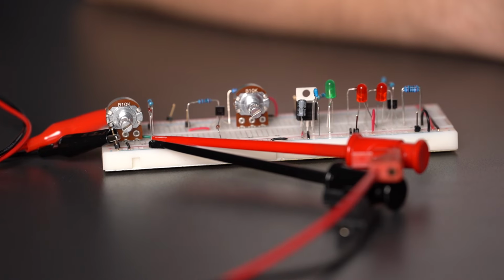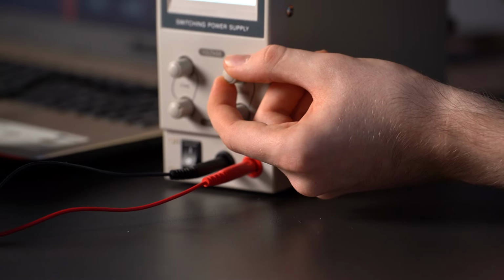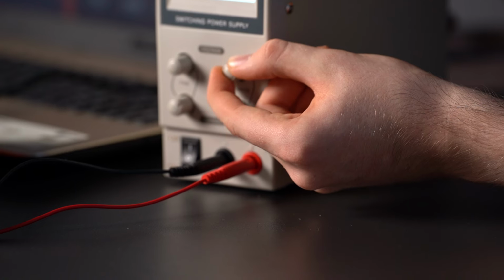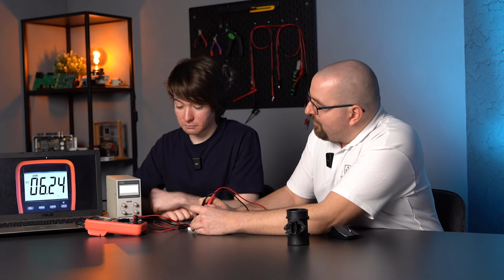Great. Now, we're supposed to see the voltage of the diode on the multimeter, and then slowly, as Marcy raises the voltage, you can see that until you get to this 6.2 volts, the voltage follows the input voltage, and you can see that it's now stopped, even though the lab supply is already at 10 volts. I don't think we should go any further to avoid a mishap here.